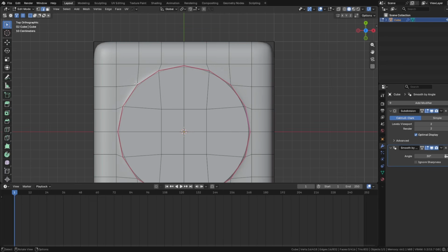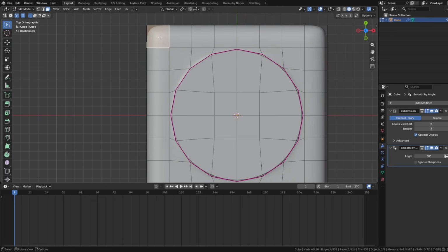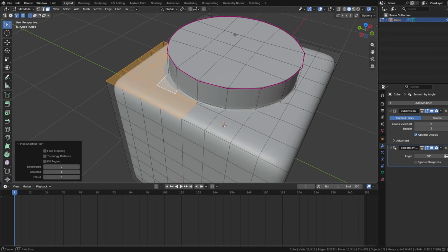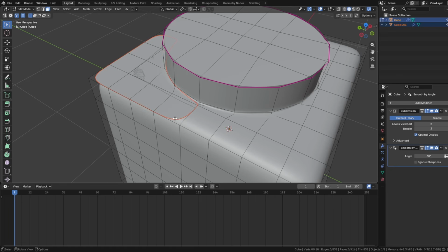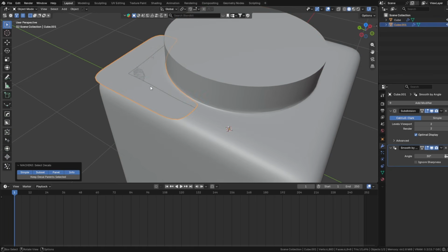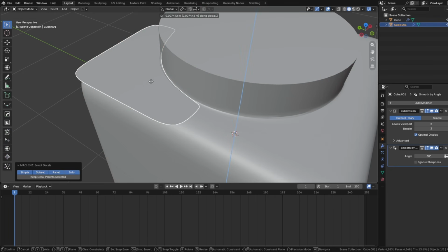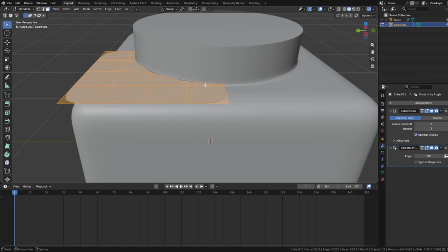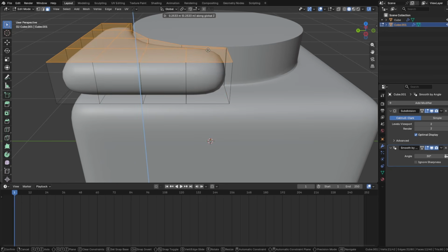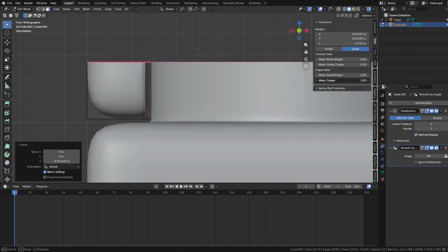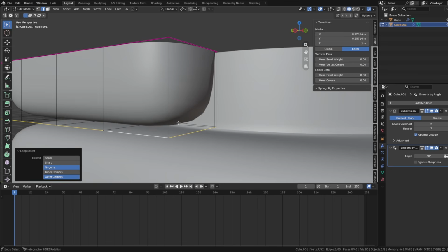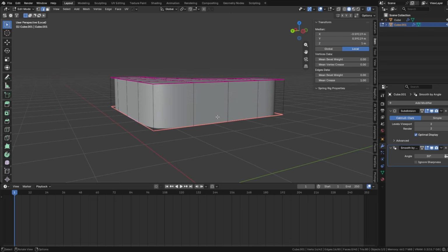And then what I did is just select some random parts here along the edges. So press Ctrl D, then P, and separate this selection. Then move this one up a tiny bit, and in edit mode, select everything, E, extrude everything in the Z direction. Try to align on the same height. We're going to increase the same value again. If you want, you can do it in the bottom as well. Try to select everything, increase the value, go back.